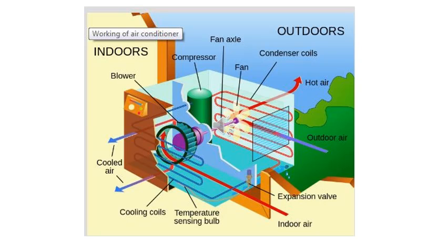Now this refrigerant in vapor form is sent into the condenser coils, where during its passage through the condenser coils, a fan blows onto the condenser coil, which removes the heat from the refrigerant and cools it, turning it into liquid form.